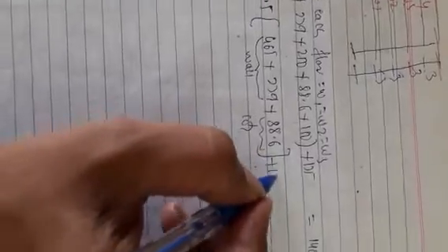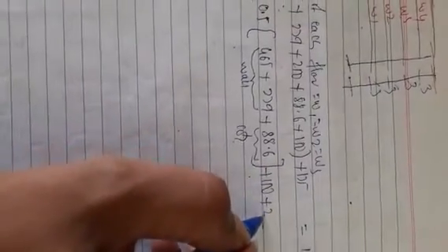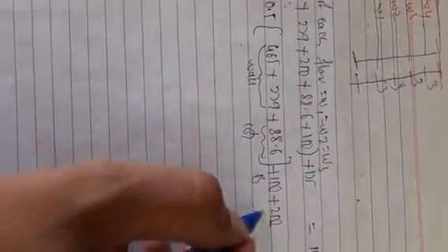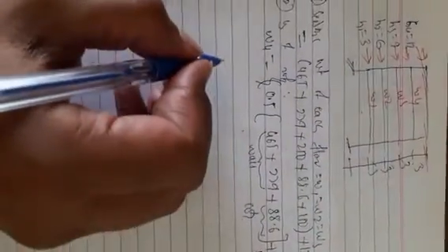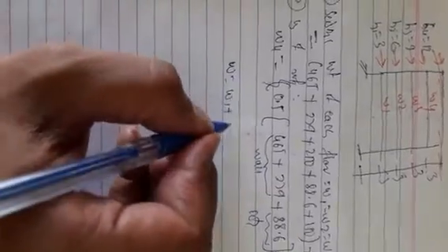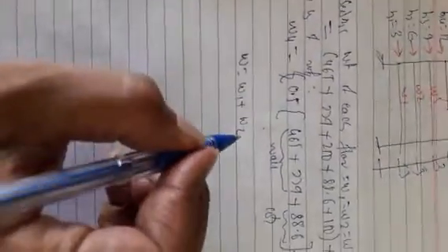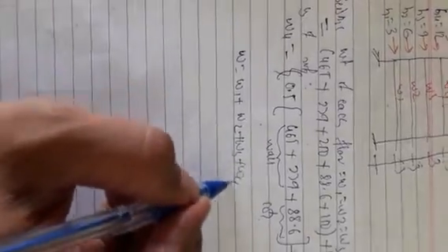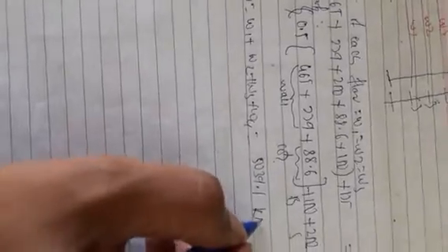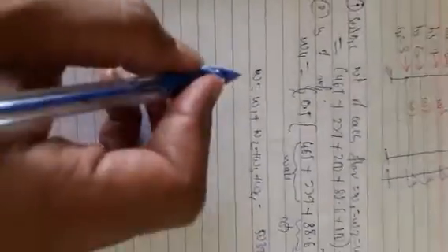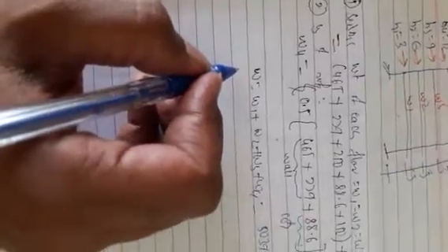Next you have to consider beams as it is 150 plus slab, this is beam, this is slab, so this works out to be 816.3 kilonewtons. So this is a seismic weight of roof, these are for each of the floors. Now total seismic weight W is equal to W1 plus W2 plus W3 plus W4, this comes to 5039.1 kilonewtons.